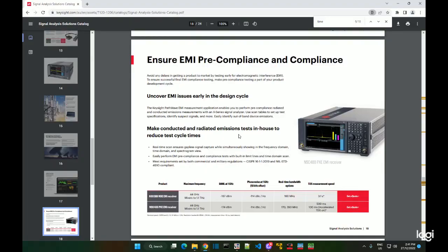This video I'm going to show you how to set up the time domain scanning in the EMI pre-compliance or compliance setup. As we know, when we're doing the scanning in EMI measurements, it may take some time, especially when you set the trace measurements to quasi-peak, because they need to charge and discharge. But according to CISPR 16, there's a way to improve that sweep time, by using time domain scanning.